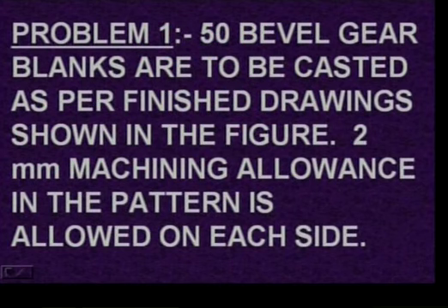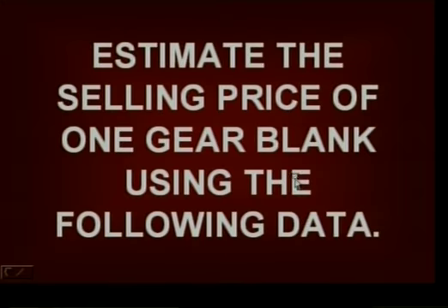Now, the first problem: 50 bevel gear blanks are to be casted as per finished drawings shown in this figure. 2 mm machining allowance in the pattern is allowed on each side. Estimate the selling price of one gear blank using the following data.